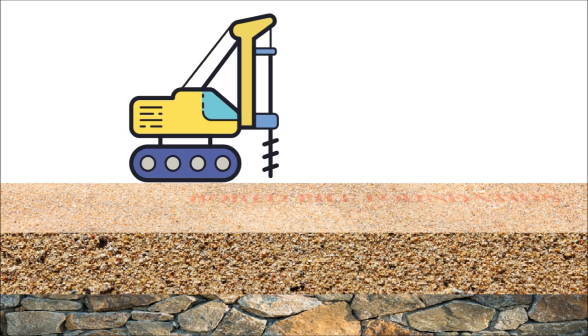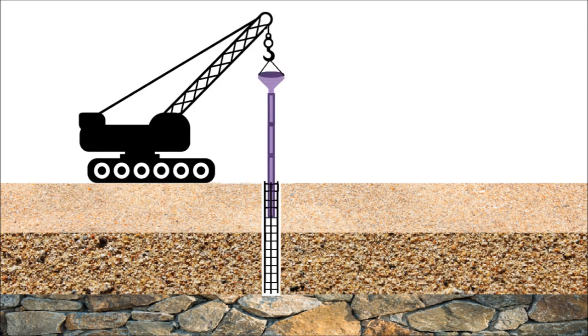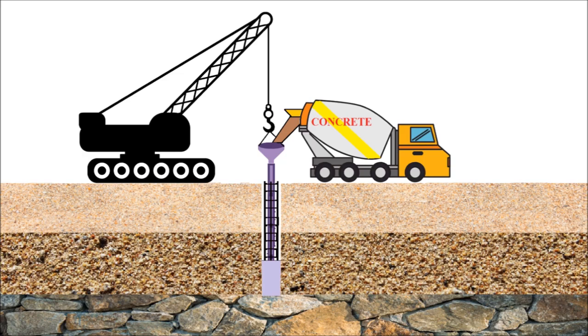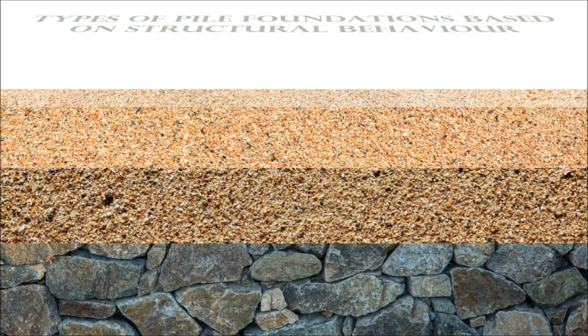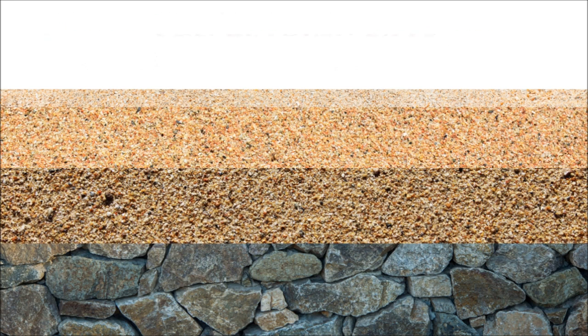Bored pile foundation. These piles are constructed by drilling holes in the ground up to the required depth, then inserting the reinforcements as per drawing and the tremie pipes as per requirement, and finally filling the hole with fresh concrete. Types of pile foundations based on structural behavior.